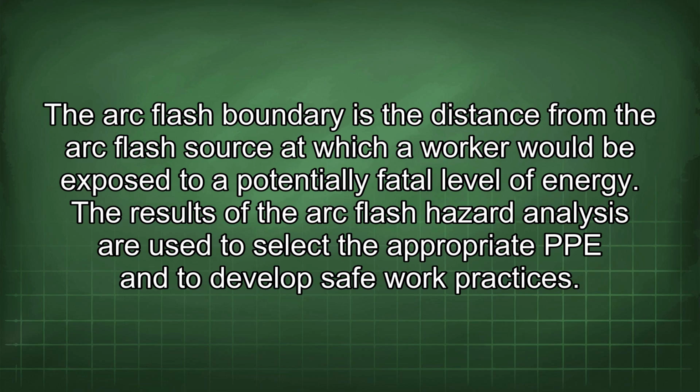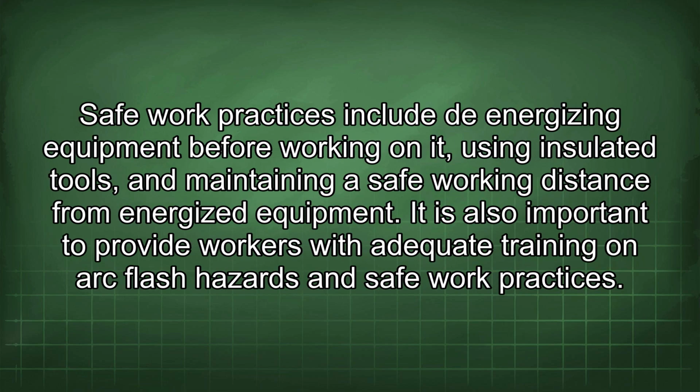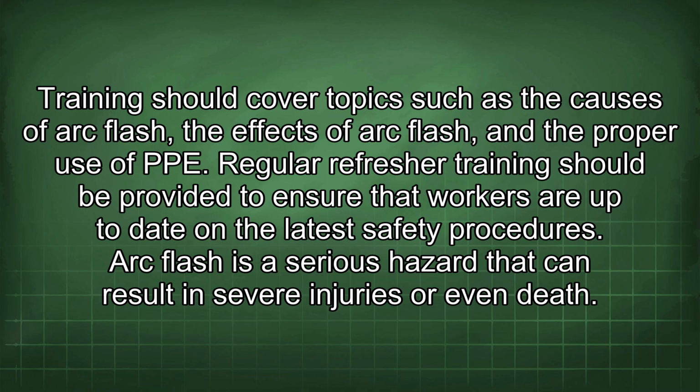The results of the arc flash hazard analysis are used to select the appropriate PPE and to develop safe work practices. Safe work practices include de-energizing equipment before working on it, using insulated tools, and maintaining a safe working distance from energized equipment. It is also important to provide workers with adequate training on arc flash hazards and safe work practices. Training should cover topics such as the causes of arc flash, the effects of arc flash, and the proper use of PPE.